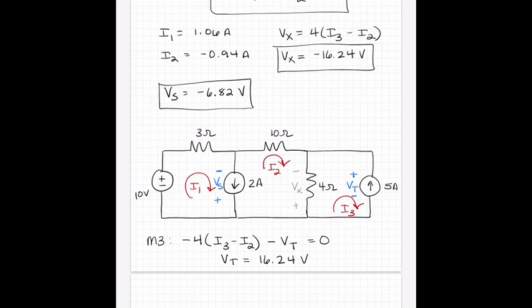But I reversed the polarity to provide that voltage to get that power delivered. Okay, so if you recognize that, you could have saved yourself a step. If you didn't recognize it, you wrote the equation again, and it doesn't hurt to see that I've solved for Vx and solved for the VT correctly. Okay, at least they are the same. They're just opposite in polarity, so they have an opposite sign.